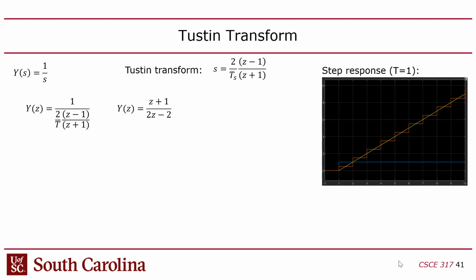You'd come up with the physics for the model, then you'd come up with a controller design, which would probably be a PID controller. You'd have to tune that, make sure it's stable, and then you could look at the step response, and the impulse response, which is the eigenfunctions, right? You calculate the eigenfunctions. And then, if you want to deploy this on a computer, you have to make it discrete, and so you're going to have to go to Z domain, okay?